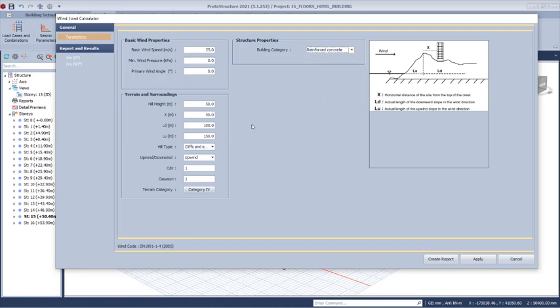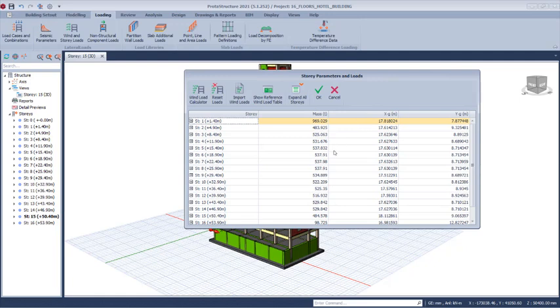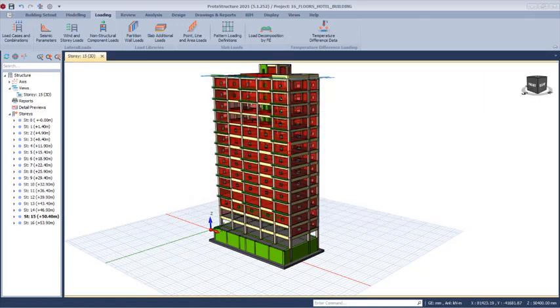After which you click on apply right there, or you can generate a report after having filled all of these provisions, and then click on the OK option. Mind you, you can overload this structure if you are not careful with the wind speed that you applied. It will also cause overloading of the structure. So all of this has to be followed properly. Click on the OK option.